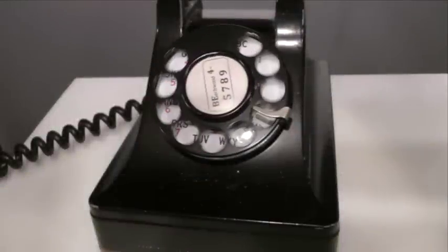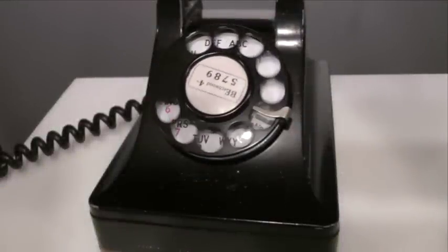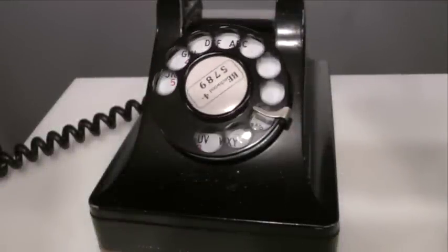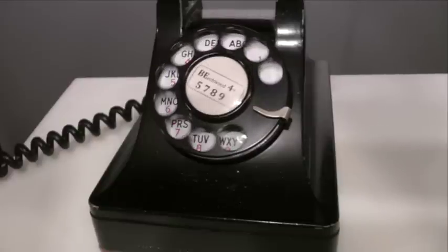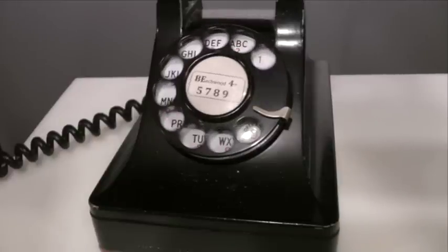As the dial continues to return, for each remaining dial pulse of the units digit, the A relay releases, the rotary armature and its pawl operate, the shaft and its attached apparatus rotate by one step, then the A relay operates and the rotary armature and its pawl release.